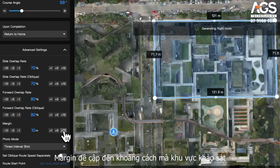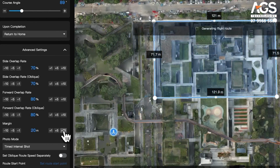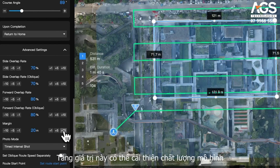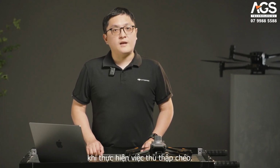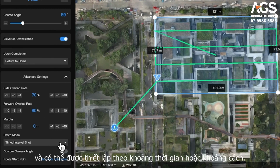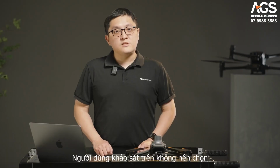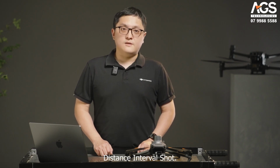Margin refers to the distance by which the survey area is extended outward. Increasing this value can improve the model quality at the edge when doing oblique collection. Photo mode refers to the photo taking method during the mission and can be set to time intervals or distance intervals. Aerial survey users are suggested to choose distance interval shot.